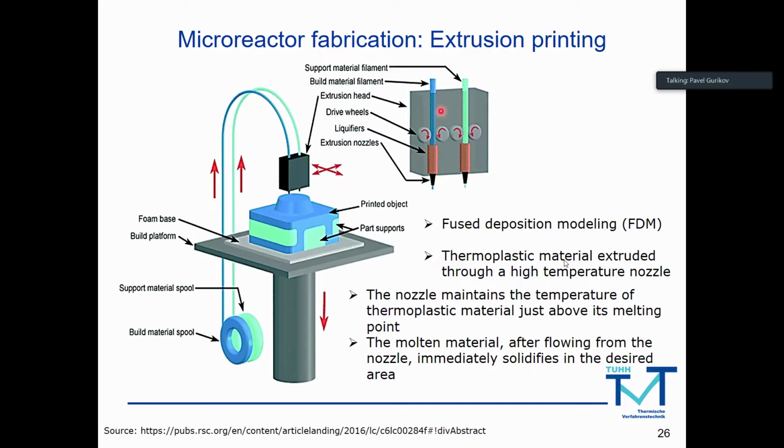So you have a heating element, and before that the polymer just passes through this ring, which is a hot ring, getting molten, and then you have a small nozzle which doses the molten polymer. So the precision is determined not by the nozzle, well, to a certain extent by the nozzle itself, but also by the mechanics.